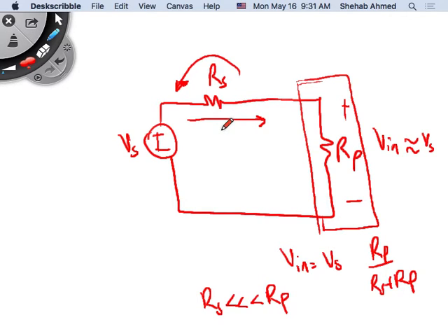It measures the physical phenomena and gives you a signal that is current or voltage. In this case, it's giving me a voltage at the output that is proportional to this physical phenomena, and it's giving me a small value of current. The small value of current is fine if I don't need a high value of current to actuate something.